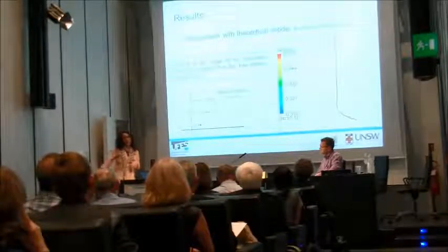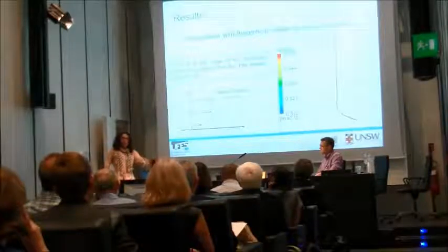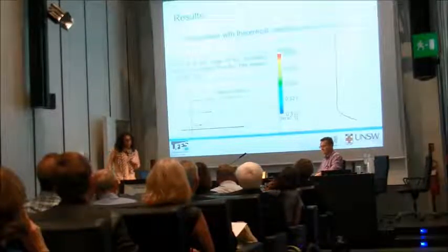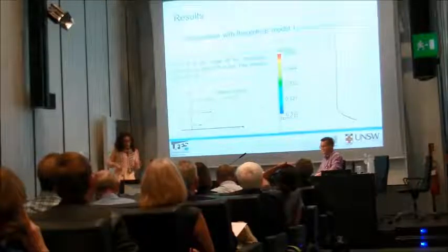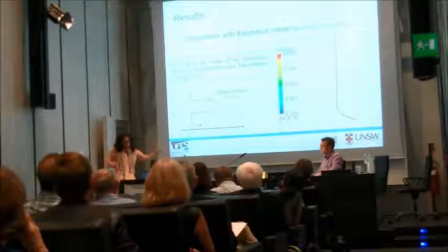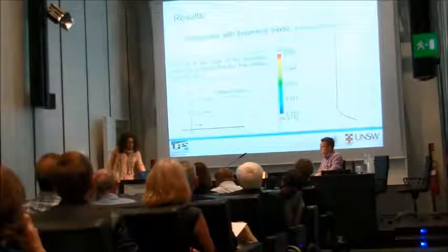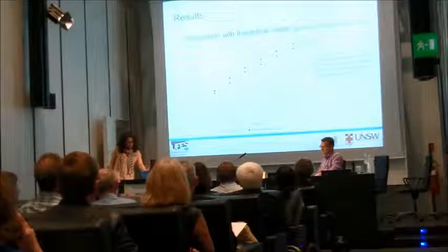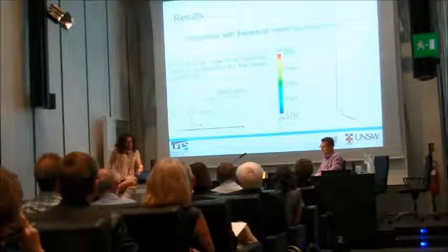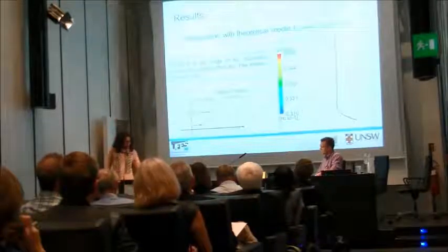We have either to increase the velocity or to decrease the velocity. We show that we are really laminar or really turbulent. And then because the section is not very long, the flow is not well developed. That's why we have difference between this analytical solution and the numerical results.